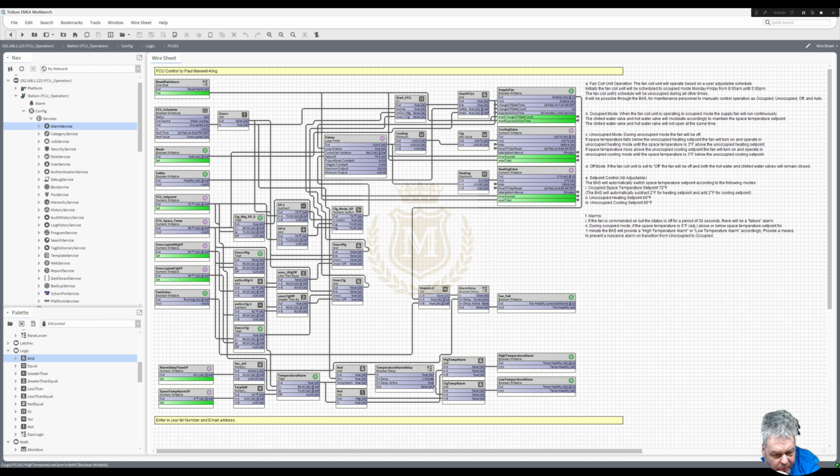And it would come up high temperature alarm. But that's because we just turned it on. So what we want to do is we want that on delay time to change itself because we're going to get that alarm in a bit.